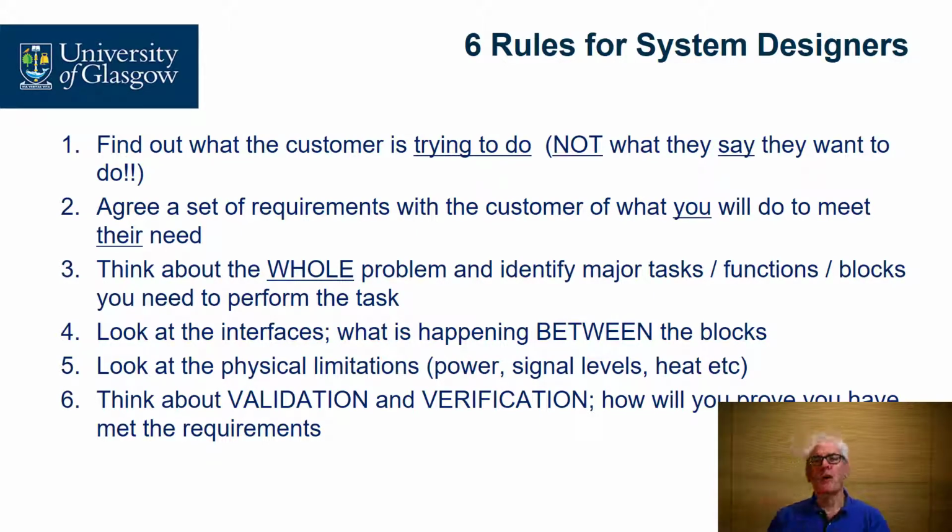Think about the whole problem and identify the major tasks, functions, blocks you need to perform that task. Don't just think about the amplifiers, think about the entire problem. The 4th rule is look at the interfaces. What is happening between the blocks? And that's where you can make a difference. Number 5 is look at the physical limitations. The power levels, the signal levels, the heat. How do you deal with it?